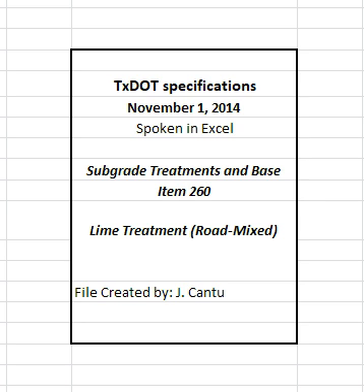3.4 Hydrated lime distribution equipment. Provide equipment to spread lime evenly across the area to be treated. Provide equipment with a rotary vane feeder to spread lime, when shown on the plans. 3.5 Pulverization equipment. Provide pulverization equipment that cuts and pulverizes material uniformly to the proper depth with cutters that plane to a uniform surface over the entire width of the cut, provides a visible indication of the depth of cut at all times, and uniformly mixes the materials.